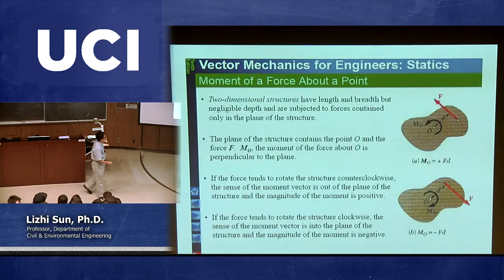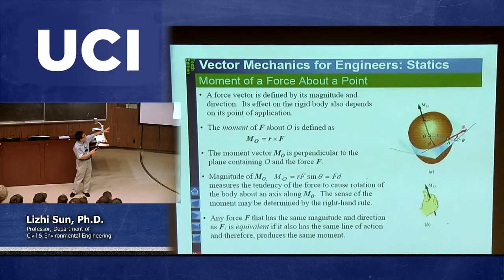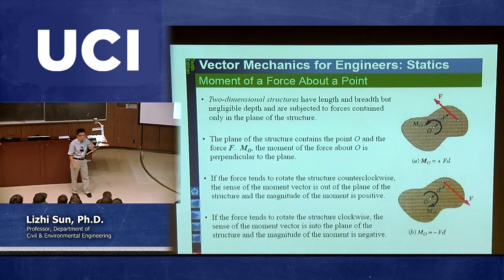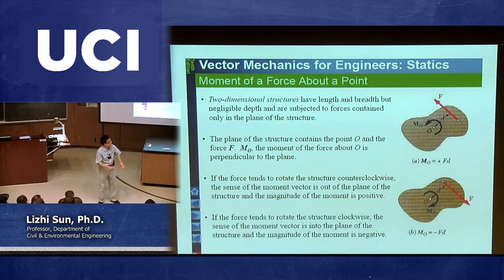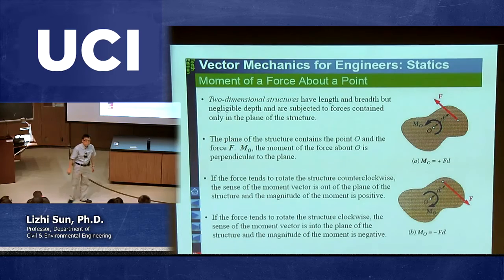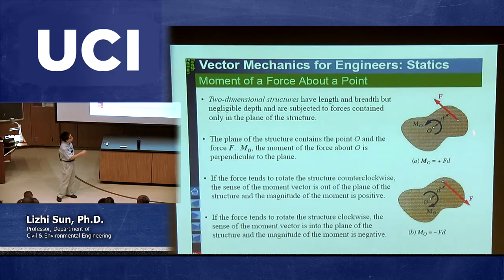However, if we go down to two-dimensional cases, there are many ways. That's why I try to let you understand that for three-dimensional moment calculation, this is the only equation. Here. But for two-dimensional problems, there are many ways, and they're really up to you. If you believe you are pretty good at catching what we call the short distance, d, then I would suggest you use this way, because this is very fast.